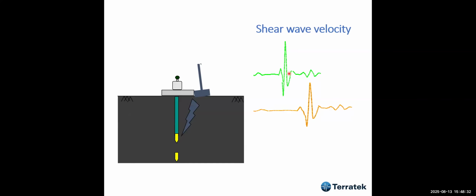We repeated the test, and this is the delta t, the difference in time, from which we can calculate the velocity in this region here, the midpoint. So velocity is delta L, which is 1 meter, over delta T, which is obtained from the plots.